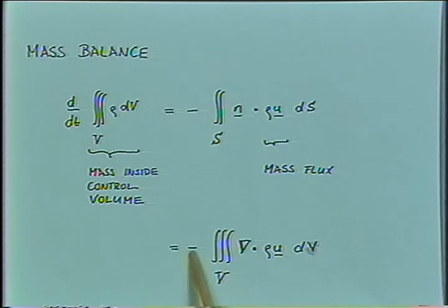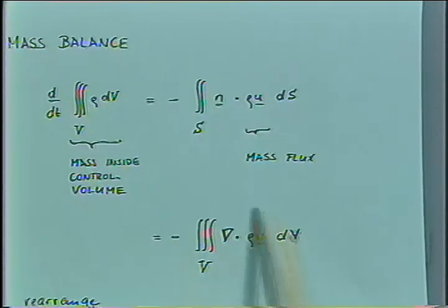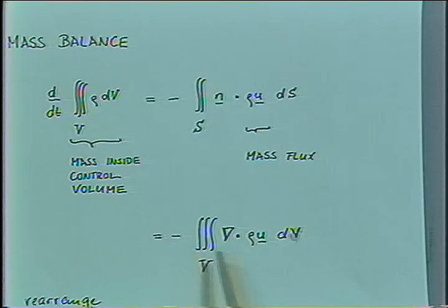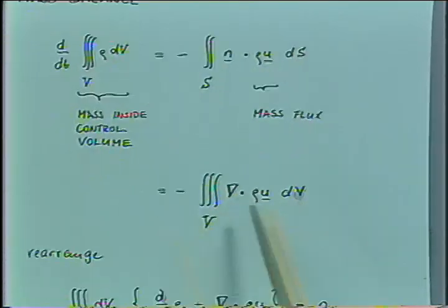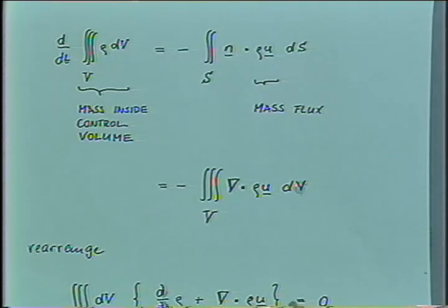plus, here there was a minus sign up here involved because the unit normal we used is pointing outward. So whenever this flux is positive, it means mass is leaving the system. So that's where the negative sign comes. So it will come over with a positive sign here, and the whole integral is equal to 0.